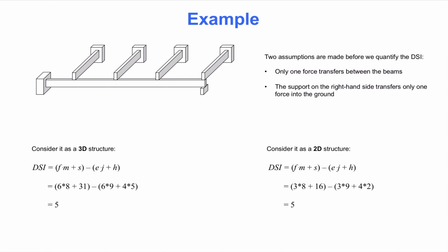In that case, there are 6 unknown forces for each of the 8 members. Notice that we count the members between all joints separately. There are 6 reaction forces in each of the 5 fixed supports, and there is 1 reaction force at the end of the lower beam. That means there are 31 reaction forces at the supports. We have 6 equilibrium equations available at each of the 9 joints. Finally, we must determine the value of H.